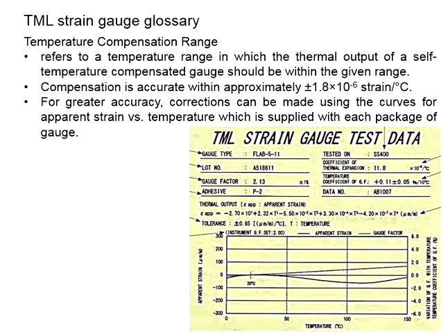Under high temperature, there will be variations in terms of the indicated strain versus the actual strain. Now, if you need to measure strain in high temperature, corrections can be made by modifying the gauge factor that you use to compute the strain in the strain gauge. It is so that the strain gauge yields greater accuracy result.